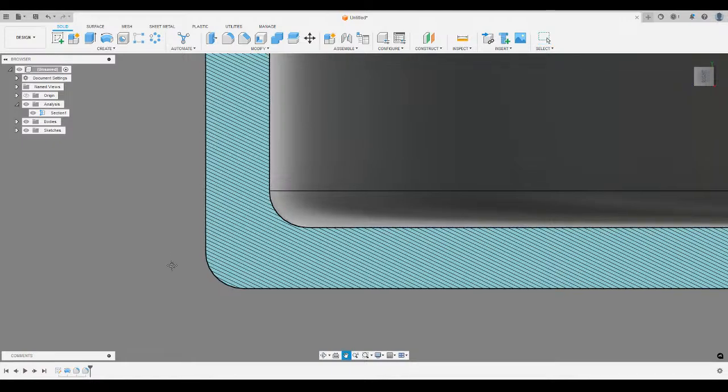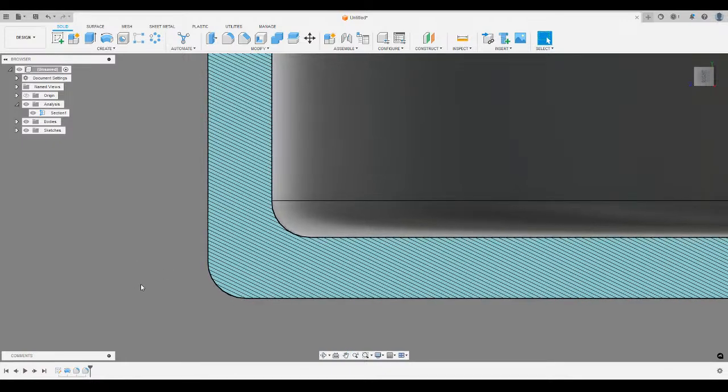And it might not be super easy to tell, but going from this wall up here that's 5 millimeters thick to the bottom down here that's 5 millimeters thick, this area in the corner right here, where it transitions from wall to bottom, is thicker from this point to this point. It is thicker than 5 millimeters.